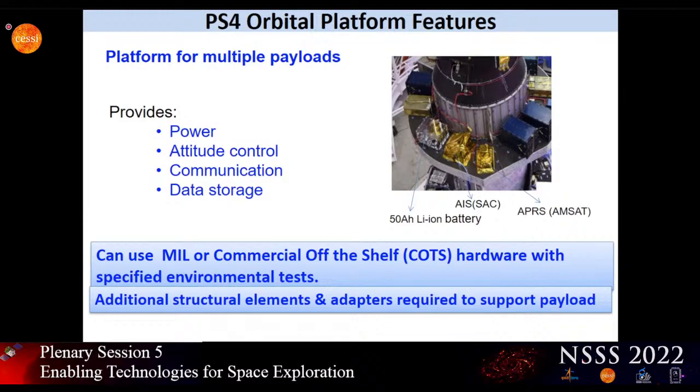There are certain environmental conditions, for example hot soak, cold soak, thermal cycling, thermo vacuum, shock, and vibration. All those things it has to undergo, because the spacecraft is going to face all that. But it is proven that commercial off-the-shelf items will satisfy all those things. The second main thing is that radiation hardening is not required here, because that is what makes space grade components much costlier.